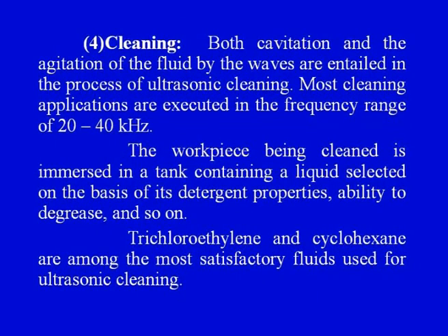The workpiece being cleaned is immersed in a tank containing a liquid selected on the basis of its detergent properties, its ability to degrease, and so on. Trichloroethylene and cyclohexane are among the most satisfactory fluids used for ultrasonic cleaning.